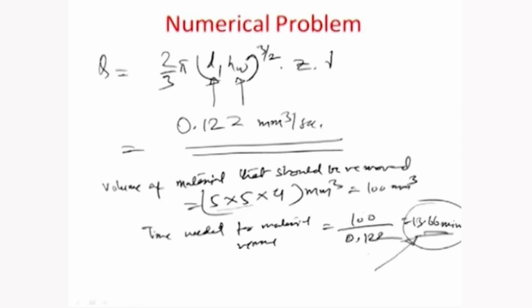So, it is really not a very high yield process in comparison to some other method like maybe drilling, which exists in the conventional world, but the advantage here, as I told you, is that you can really focus very narrow using masking technology, and you can also ensure that you have a reasonable amount of surface finish, or surface roughness in microns or in a fraction of a micron, which can come automatically by virtue of the nature of the process.